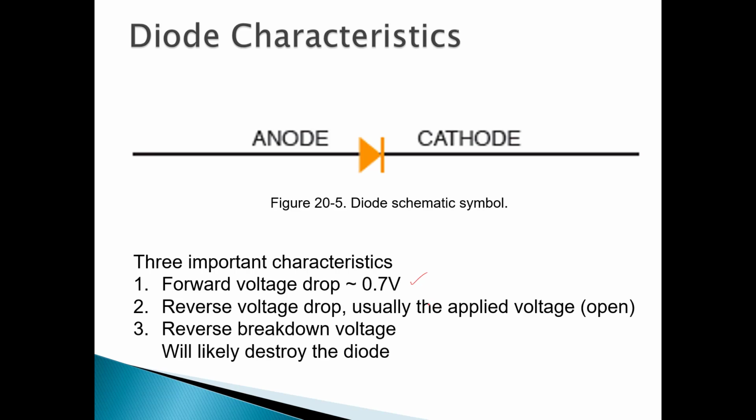Then there's this reverse voltage. If I put the voltage on backwards, I turn the diode off and it's like an open circuit. So between this plus 0.7 and backwards, we can use the diodes as a switch. A real cheap and easy switch that allows current and then disallows it. And then if you reverse it a bunch, you likely destroy the diode this way, okay?